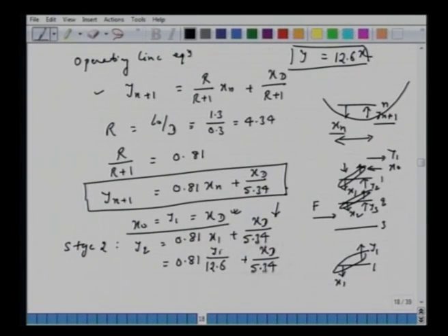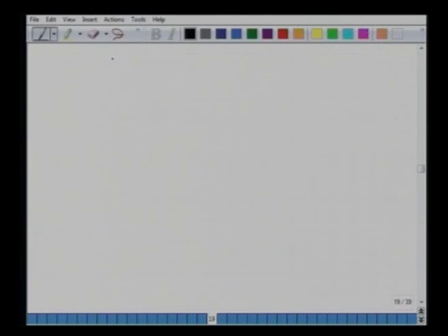But what is y1? Remember, this y1 arrives from the top plate to the condenser. We have a total condenser, so y1 is the same as xt. So we can substitute y1 here with xt to simplify these equations as y2 = 0.25 xt. Now we have another expression which relates xt to y2.